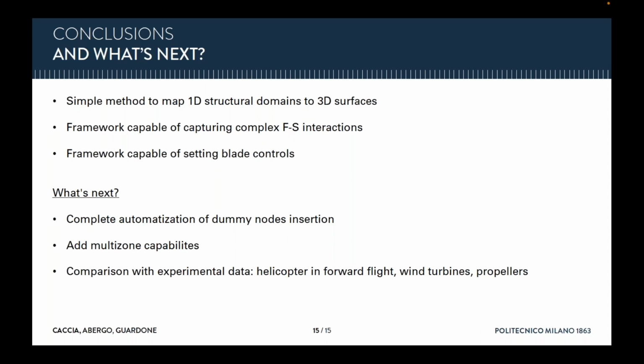And what do we still have to do? Complete the automatization of the insertion of the dummy nodes within the structural model, add multi-zone capabilities so that we can have a rigid rotation of our rotor and study forward flight with a proper mesh with a wake that is meaningful and with a small number of elements, and then do some comparison with